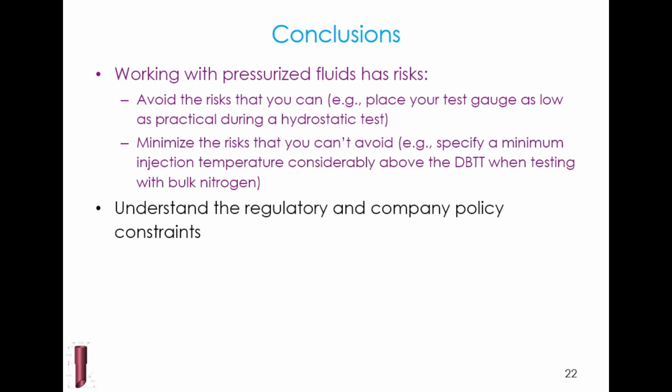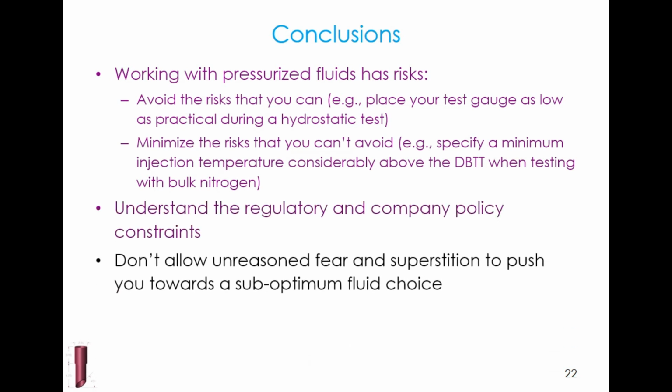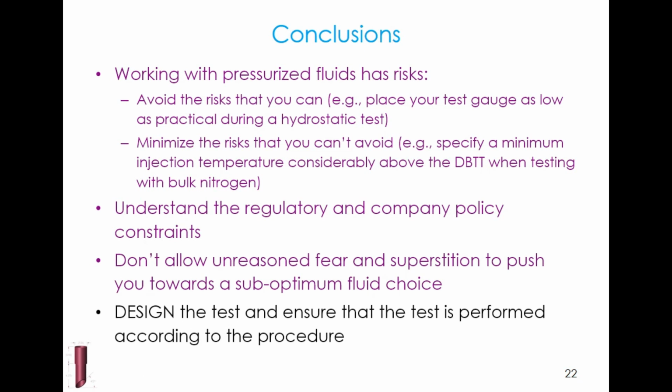You want to understand the regulatory and company policy constraints. Don't allow an unreasoned fear and superstition to push you towards suboptimum fluid choice. You want to design the test and ensure the test is performed according to your procedure. Too many engineers spend a lot of time specifying valves by model number and specifying grades of pipe and mill runs and mill specs and on and on and on. And then at the end of all this specifying, they say, and test to 900 pounds for 2 hours. Leave everything to the field to make all the decisions, and you get what you deserve.